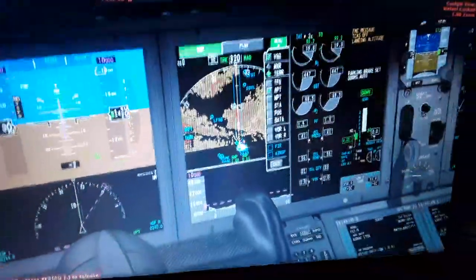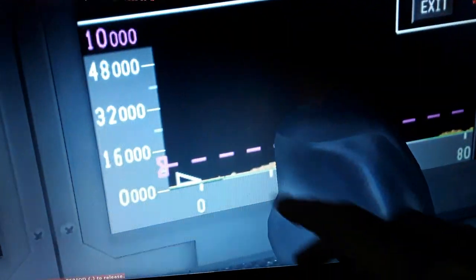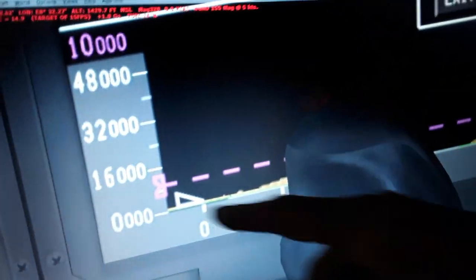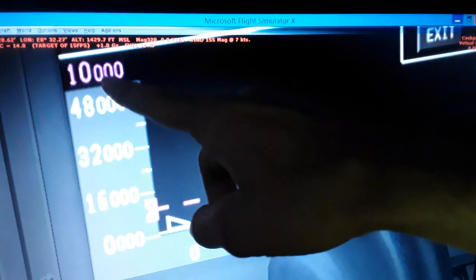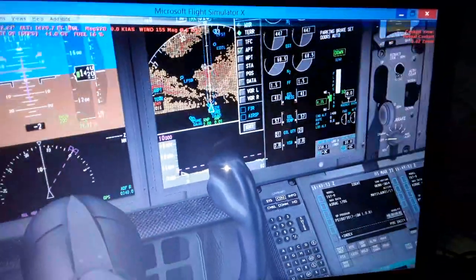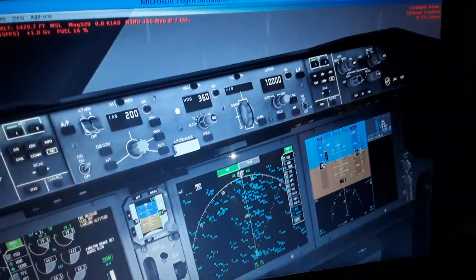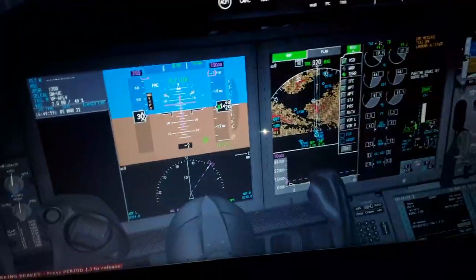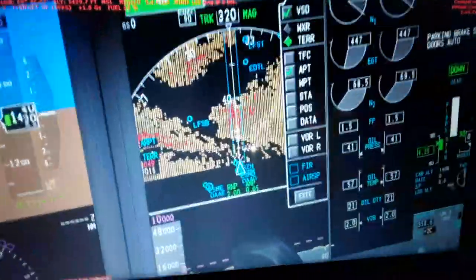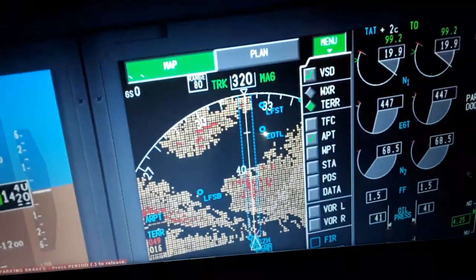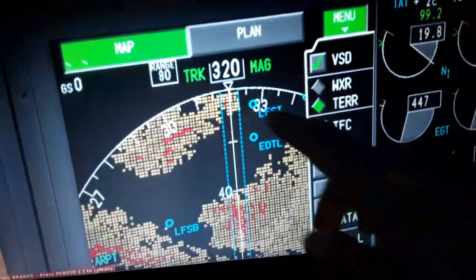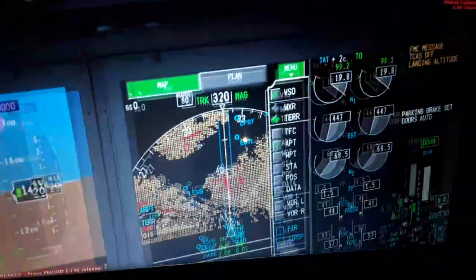You will see later, you can see also the vertical over here. That was the horizontal. You can see how many thousand feet above the ground level. You can see 10,000 like in the autopilot. This line is 10,000 feet like the one we have selected over here. So you can see the range is 80 nautical miles. The ground speed, and you're going to see the wind direction and speed when we fly, the magnetic north pole and geographic north pole, and the magnetic variation depending on where we are in the world.